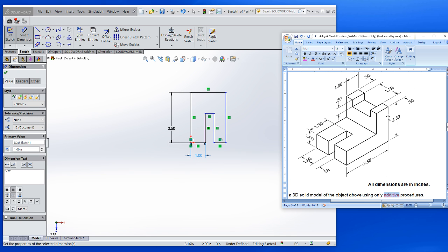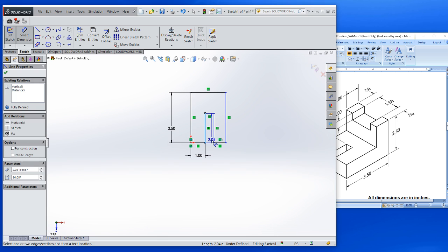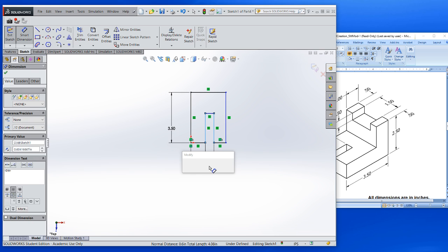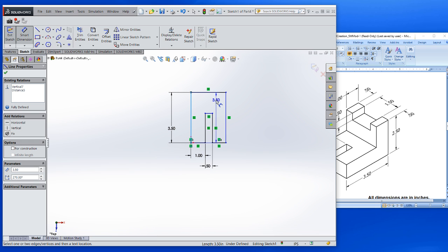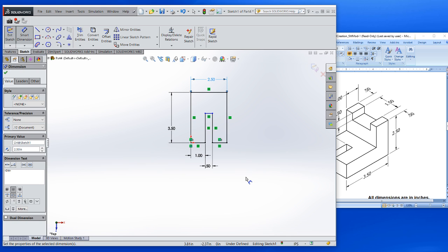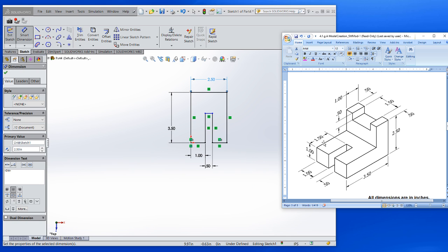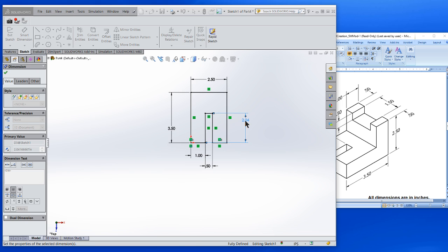The overall width of the model, this is 1/2 inch. And if you add these up across the top, what you're going to see is this is 2.5 inches across, which makes this, I'll just come across here and call that 2.5 inches. That defines everything except the height of the saddle, and it is 1.5 inches to the height of that saddle. At that point, I'm fully defined.